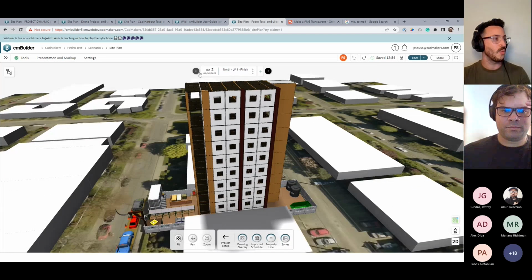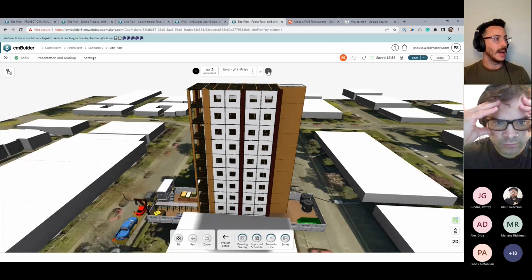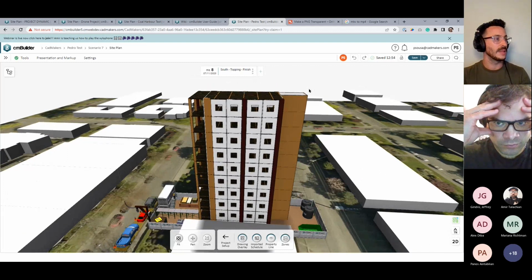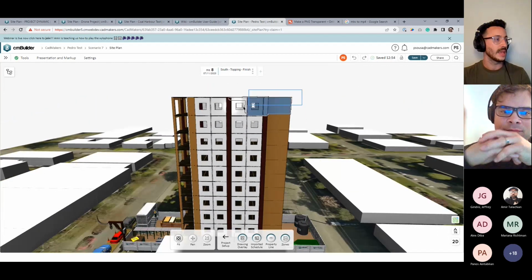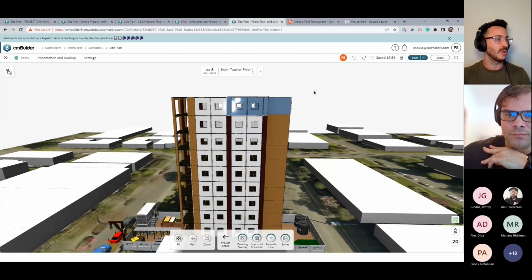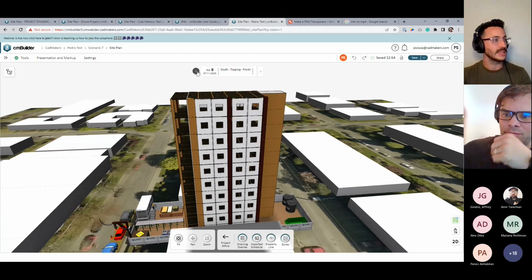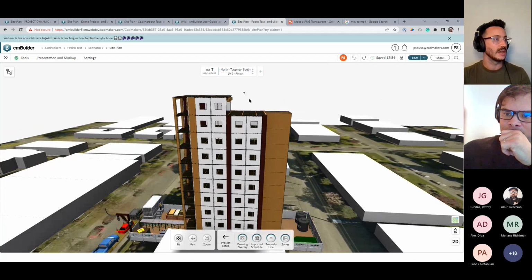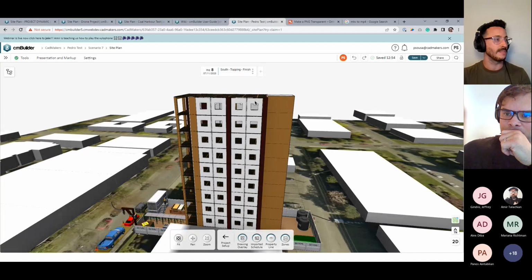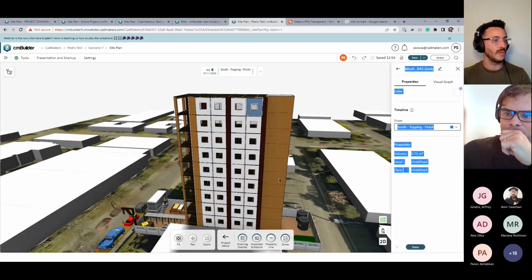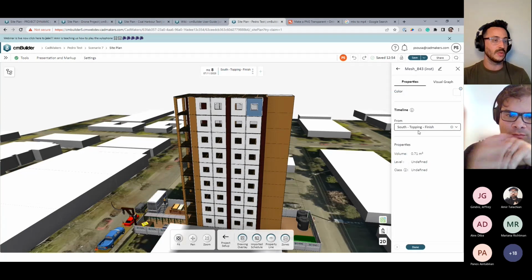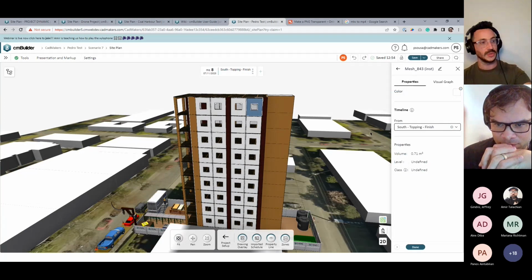So let's say that I want to define that on my last milestone, the south of this building is going to be concluded at this stage. So I'm going to right click and say begin from this milestone. It means that now all those parts are going to be executed on that milestone, and I can see them over here. If I edit the model element, I can see the milestone to which that element is assigned, right?